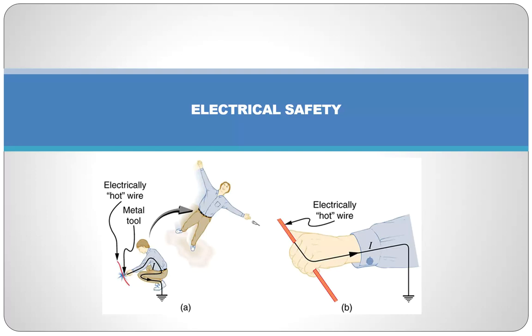Current going across the chest. I don't know how I mess up words, but it happened. So that's a bad way to go. So if you were to grab something and have that current going through you, and it went from this hand to this hand, it'd be going across the chest, and you would potentially have that suffocation risk.